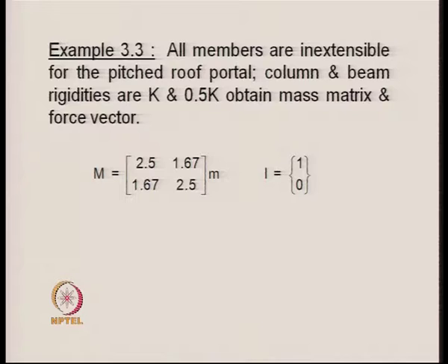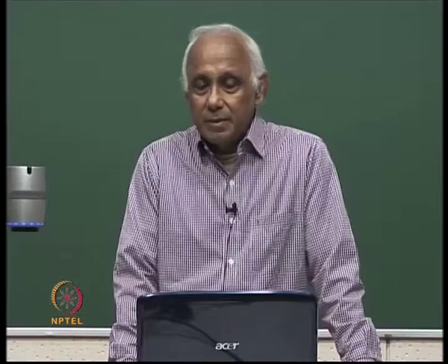Then these two equations can also be written in a state space form, that is, a form in which the second order differential equation is written as a set of coupled first order differential equations. The state of the system is defined by a vector consisting of displacement and velocity, and both state space equations can be written, one in terms of the relative displacement, the other in terms of the total displacement.